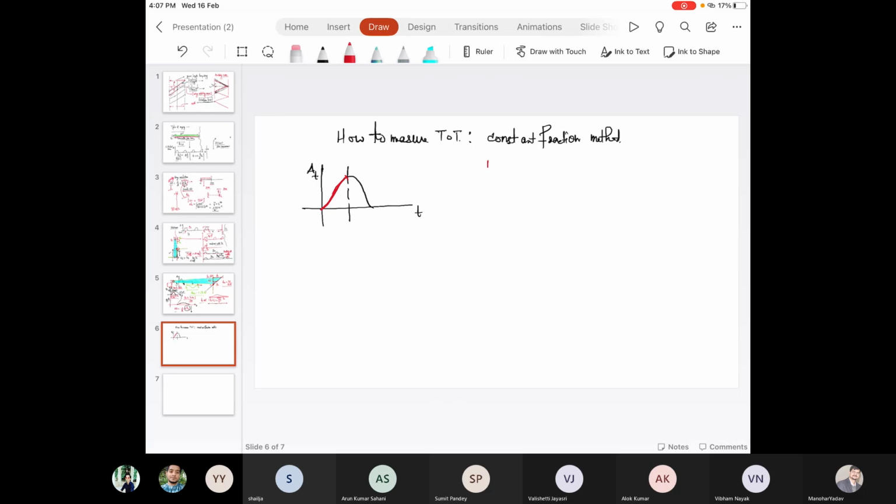Okay, so first, just see the analysis. What we do with respect to a specific point on the leading edge, we generate a trigger signal to initialize the counter circuit. So the time counter is started by a transmit pulse, and the time counter stops when the voltage reaches a predefined, specific value for a received pulse.